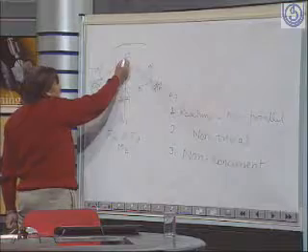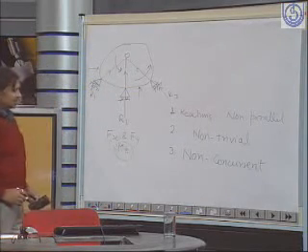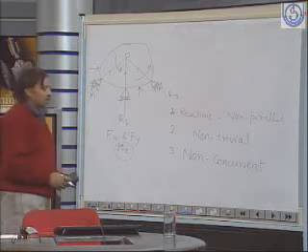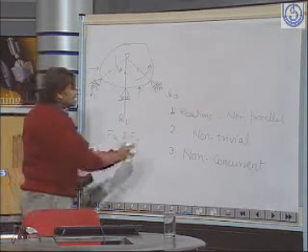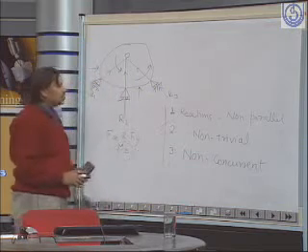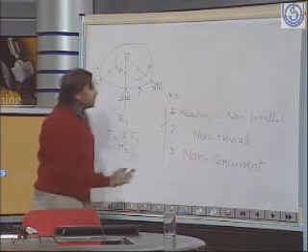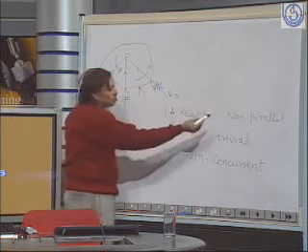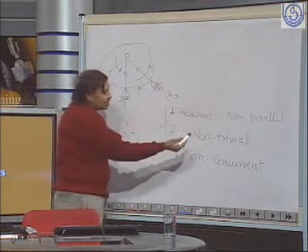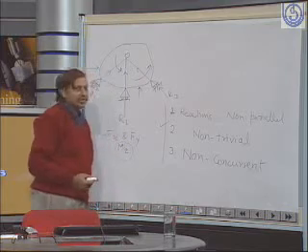If they are meeting at a point, it will not be able to provide this constraint. So if we translate it in these three necessary conditions, they come out to be that reaction components or reactions should be non-parallel, they should be non-trivial, and they should be non-concurrent.